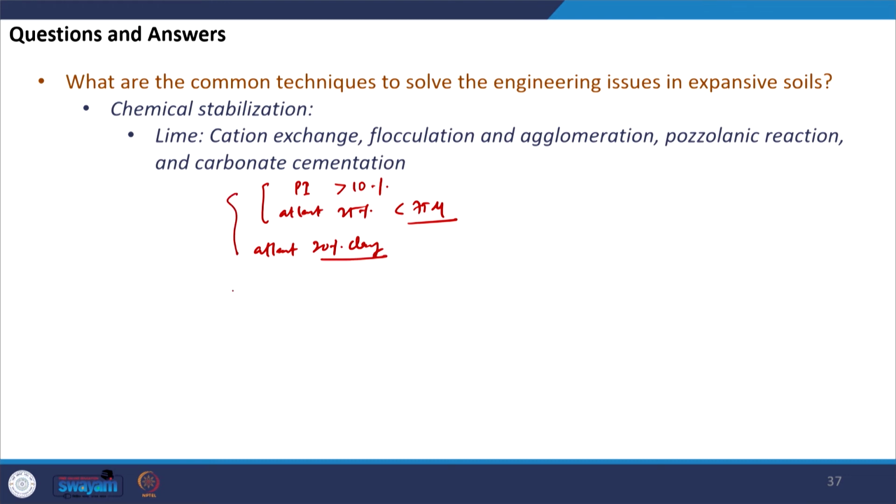If you talk about the dosage of lime, then 1 to 3% is typically required for adsorption, that is the first part, adsorption during the cation exchange process. Okay. And this amount is required for complete adsorption of Ca2 plus to take place. This is called the lime fixation point. Then we also need additional lime for further pozzolanic activity, all right. So, we need additional lime.